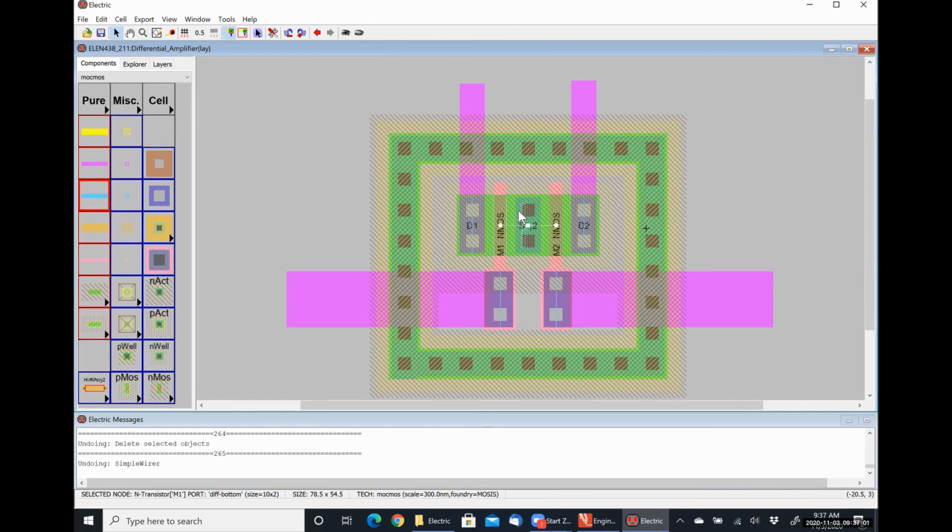So to answer Grant's question, we're absolutely going to be connecting this thing to a current source. What we're going to be connecting it to is our current mirror that generates our reference current, right? That's why we made it. And we'll worry about how we're going to do that after we draw this whole shebang, and I'll show you guys a little something once I get this thing drawn in a way that's not ticking me off. There we go.